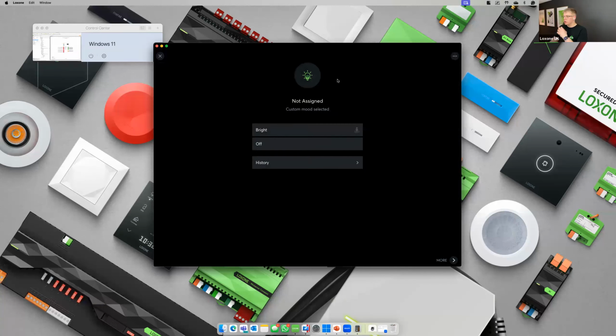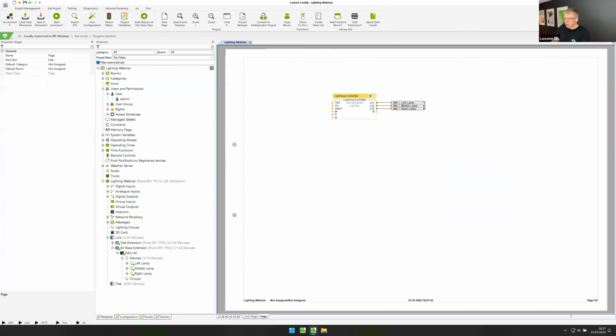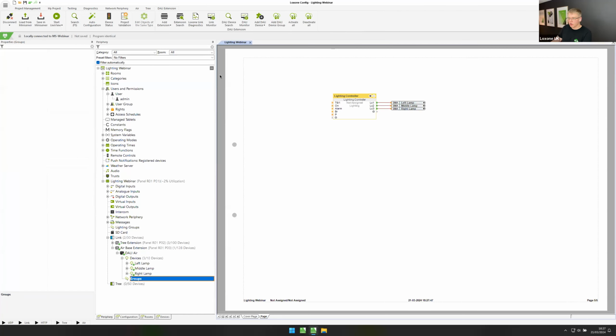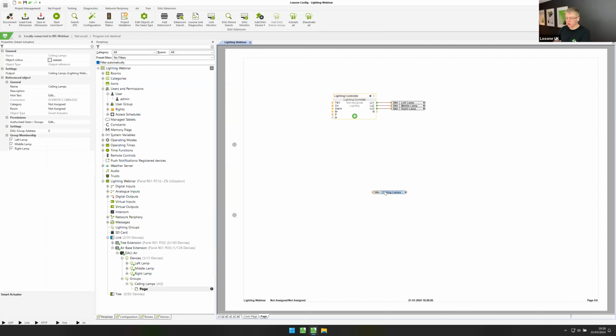But remember, we are controlling it over a bus as opposed to physical dimming with, maybe, PWM or mains phase dimming. Now, what I'll do is I'll show you the example of grouping them. At the moment, we've got our individual devices. So I can go to groups, add DALI device group, and I could name these my ceiling lamps. And then I can see amongst all of my different devices, I can then select them. So now all of these can be controlled in a group.